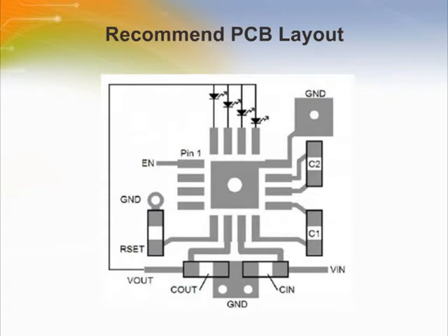In charge pump mode, the driver switches internally at a high frequency. It is recommended to minimize trace length to all 4 capacitors. A ground plane should cover the area under the driver IC as well as the bypass capacitor. Short connection to ground on capacitors C-in and C-out can be implemented with the use of multiple vias. A copper area matching the TQFN exposed pad must be connected to the ground plane underneath. The use of multiple vias improves the package heat dissipation.